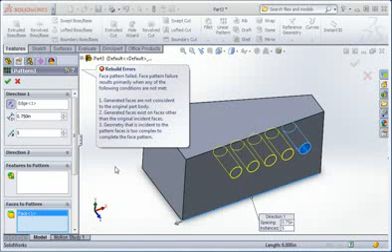So to summarize the main points of this lesson, plan for your patterns. If you intend to use a feature in a pattern, make sure the geometry in the feature is the geometry you want to use in the pattern. If you want to use a face in a pattern, make sure the geometry of the part is simple enough to use the Face option. One last thing and you'll be finished with this lesson.